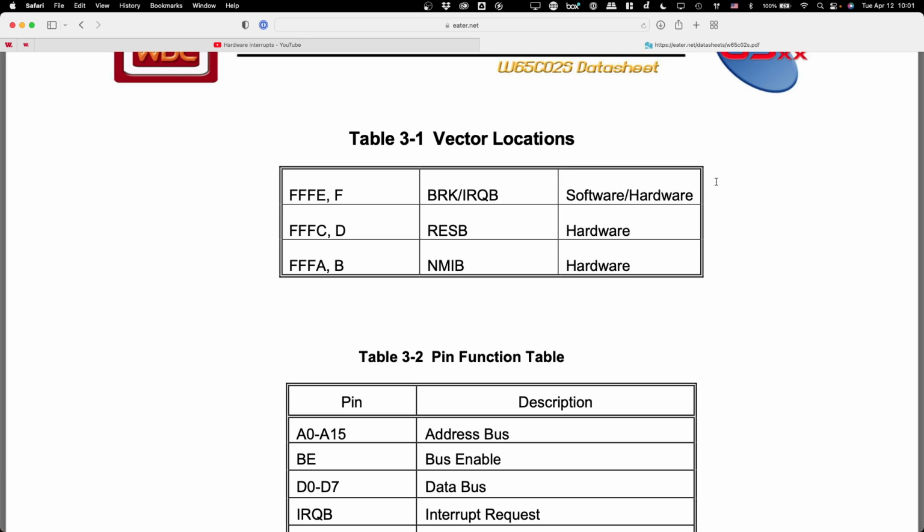yeah. So let's say, for example, we had a second clock module. We just built a clone of the clock modules we already have. So what Rippy is suggesting is that we have one of the clocks control the processor, just like normal. And then we tie the other clock to the interrupt pin so that every particular amount of time we're triggering an interrupt. We don't have to actually do it that way, but you could.